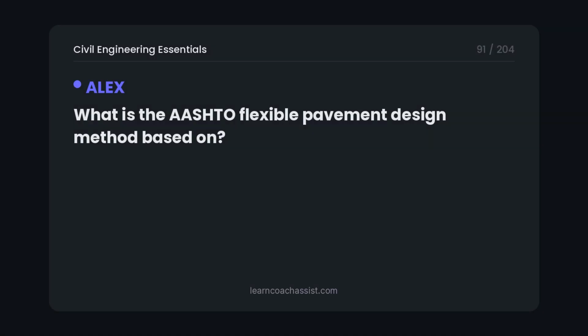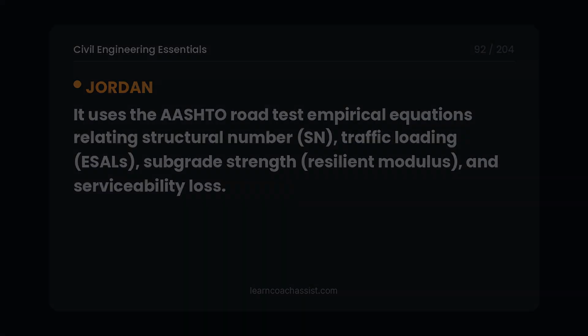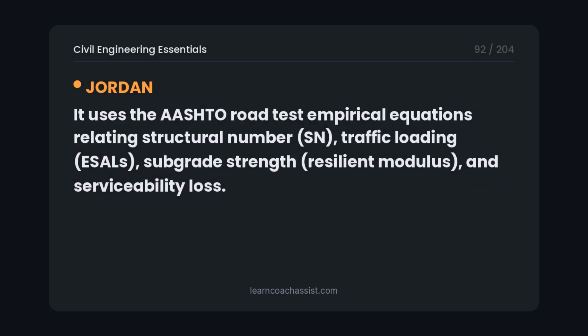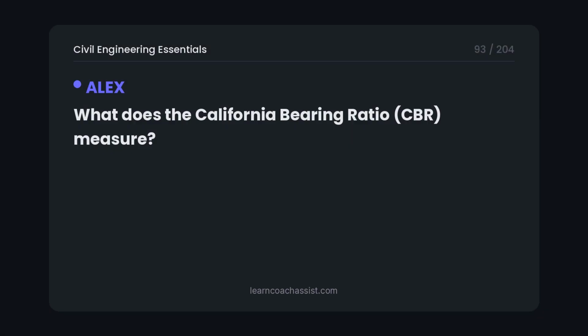What is the AASHTO flexible pavement design method based on? It uses the AASHTO road test empirical equations relating structural number, SN, traffic loading, ESALs, subgrade strength, resilient modulus, and serviceability loss.